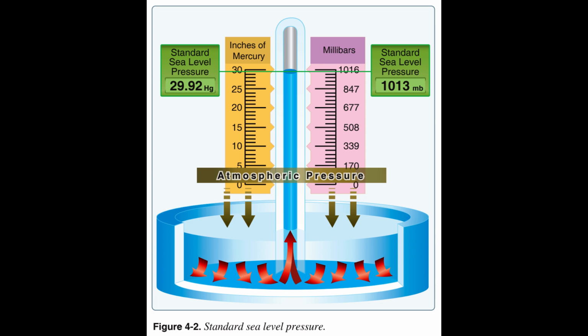There are no rules of thumb that can be easily applied, but the effect of humidity can be determined using several online formulas. In the first example, the pressure is needed at the altitude for which density altitude is being sought. Using Figure 4.2, select the barometric pressure closest to the associated altitude. As an example, the pressure at 8,000 feet is 22.22 inches of mercury.